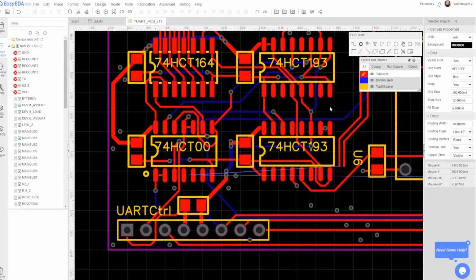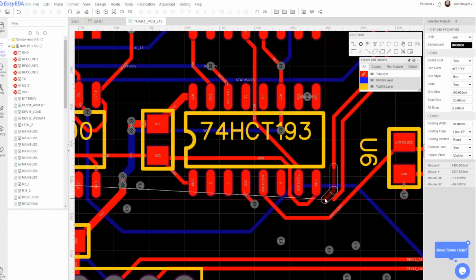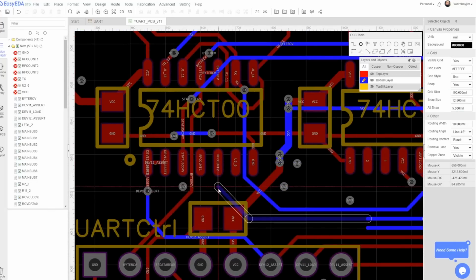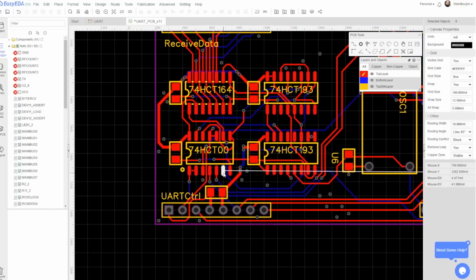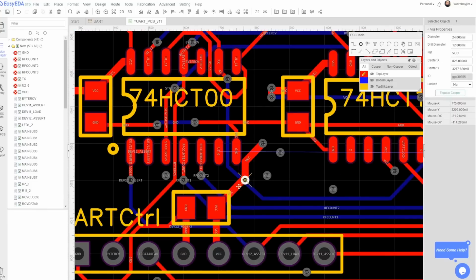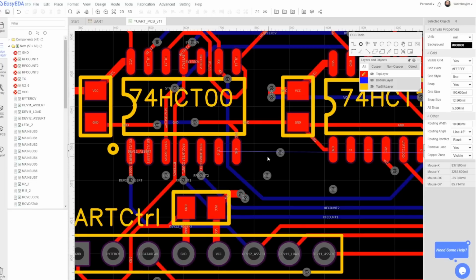This PCB was from before I started to use 4-layer boards. So I'm going to transition this to a 4-layer board, which is going to make this all a lot easier. We'll actually have a ground plane and a power plane to take care of all of this. Just need to get a good connection to the plane after the capacitor.